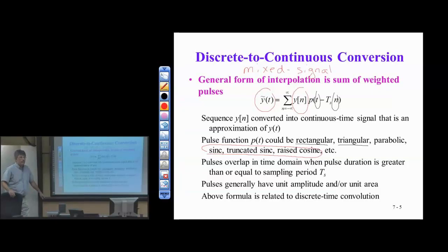Right, remember from the sampling theorem, when we derived that in lecture 4, the ideal reconstruction is from an ideal low-pass filter, provided that we have obeyed the sampling theorem. So if we have an ideal low-pass signal that we're sampling, a band-limited or baseband signal, here's the Fourier domain, and it is ideally band-limited.